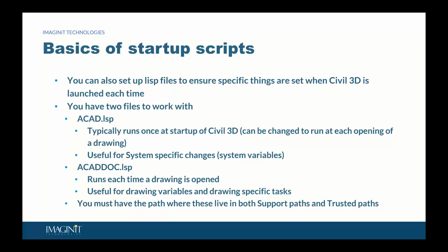So in my ACAD doc, I can set my layer back to 0. I can change all the current environment variables. I can modify that information or change certain things in the drawing without knowing who's been in the drawing before me, so that I can start the drawing the way I like when I get in. And again, these are easy things to do, and we can set this up. This comes back to that ARG and our custom settings, where we have a custom icon that launches our custom settings that are set up to point to our custom pipe catalogs, our custom survey catalogs, our custom plot styles, all of those things.